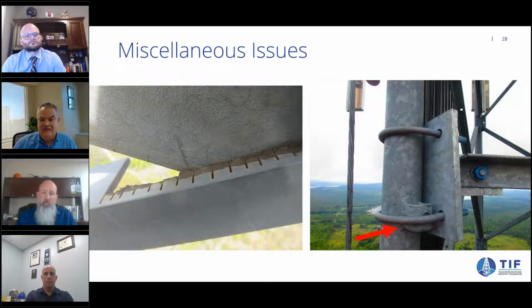John, you want to talk about the right side? Yeah, absolutely. I can't see if a step bolt was used above or below, but obviously we prefer to relocate the step bolt and hack off that attachment point so you can properly attach that sub-horizontal there.